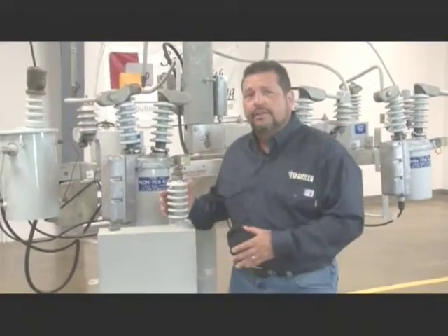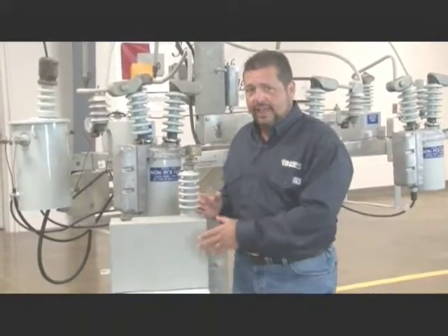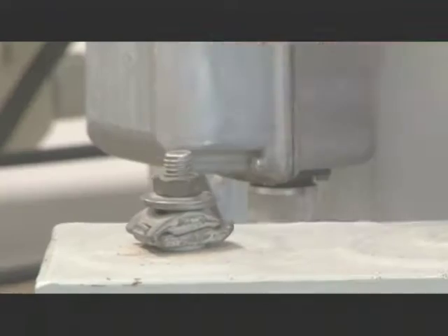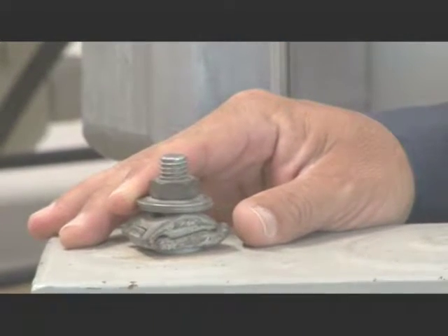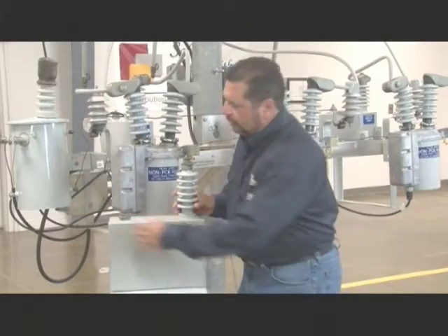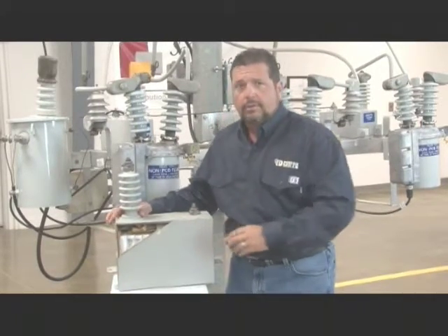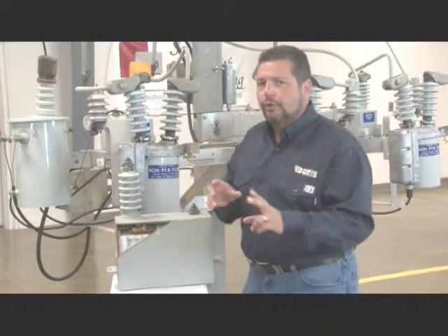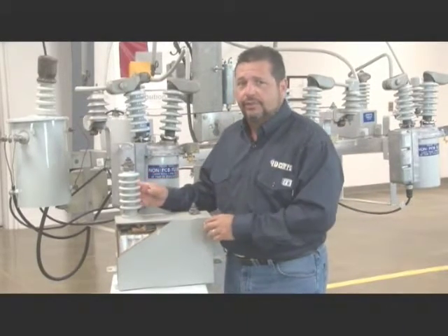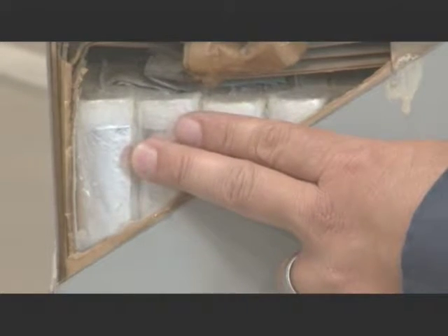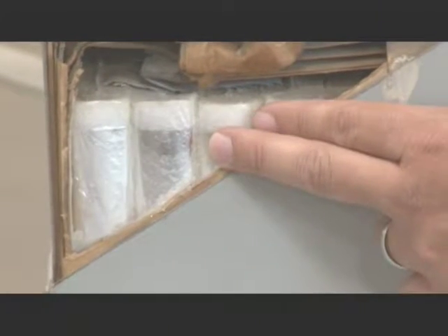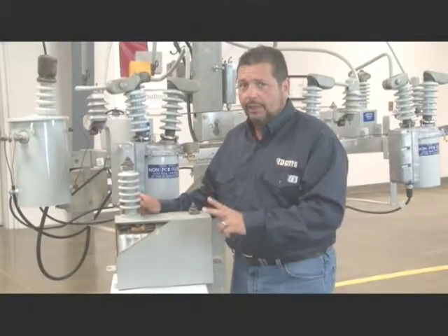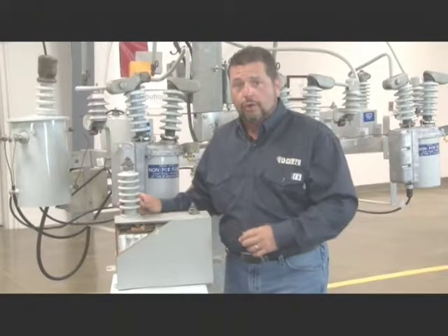This is a single-phase capacitor unit. It has a tank and a bushing that will be connected to the phase, and either a lug or a second bushing that will be connected to ground. If we turn this capacitor tank around, we can see the inside of the unit through a cutaway. Instead of two flat plates separated by a flat thickness of insulation, we see a surface that looks like it's corrugated. Each of these corrugations, or cells, is a capacitor. Each has two plates separated by insulation that is rolled up.